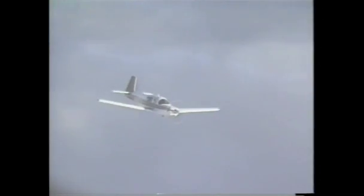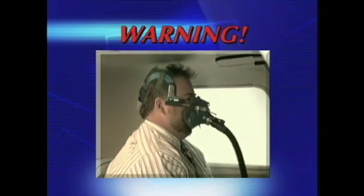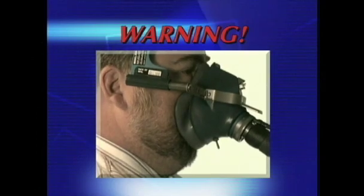If you are not familiar with the requirements concerning oxygen use in your particular operation, contact the FAA Flight Standards District Office nearest you. Warning: masks have not been qualified for wear over beards or heavy facial hair growth in accordance with FAA technical standard orders. Facial hair that crosses sealing surfaces can seriously degrade the performance of these masks.